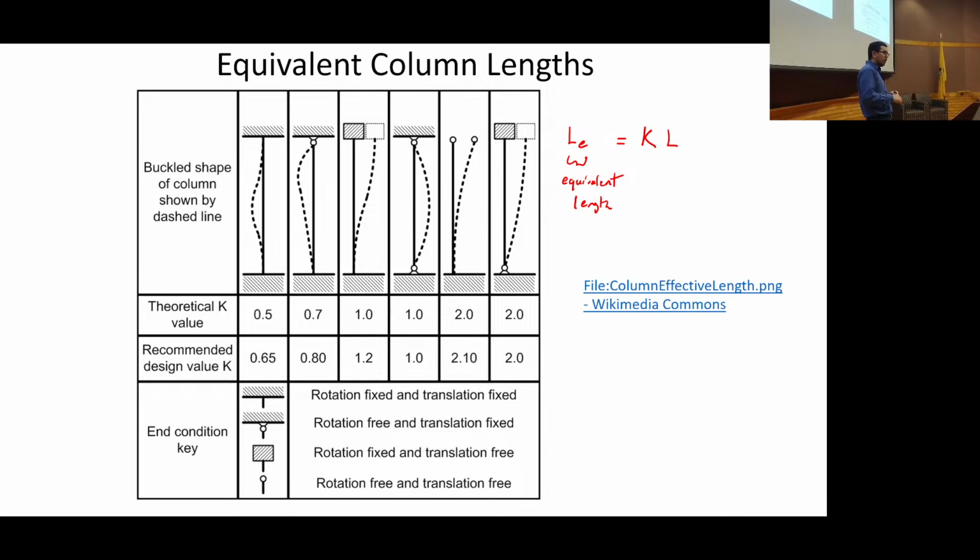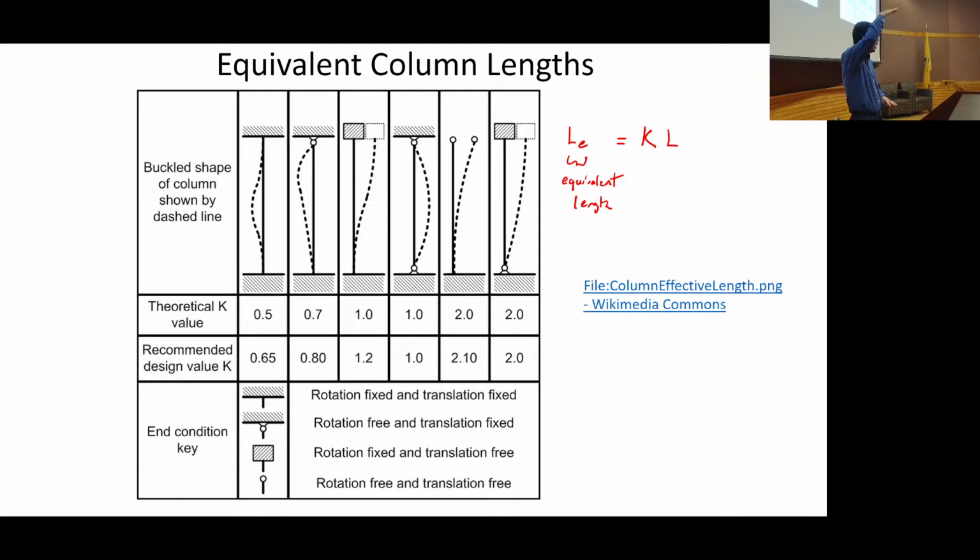These theoretical values are usually based on the Euler buckling criteria, and they're going to be used for both the high slenderness ratios and the lower slenderness ratios. So let's say that we have a very narrow, tall column, and now I make it really, really pancake fat. Do you think I even need to care about buckling? Is that even an issue?